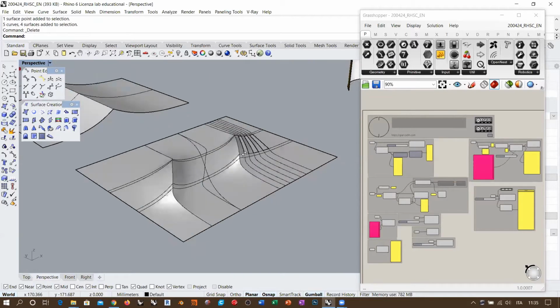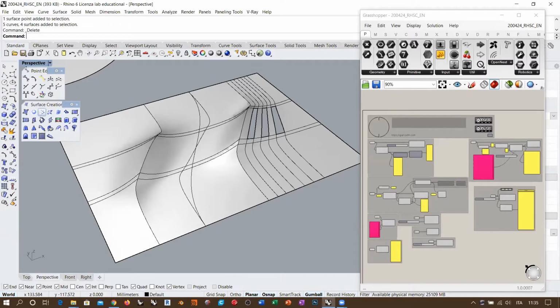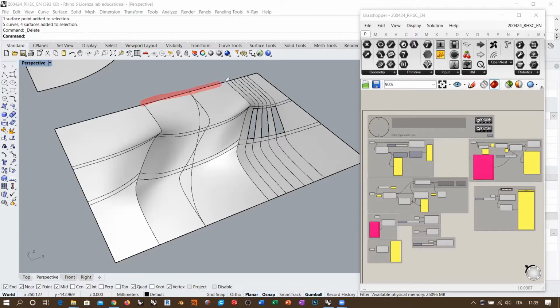And in order to create this internal surface with a traditional direct modeling method, we should at least count on, well, I will do this with an annotation, so there is no need to do it physically in Rhino, this curve here, and then this side crease, this other side crease here, this valley line, which is going to be this one.